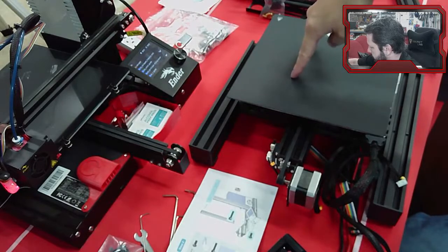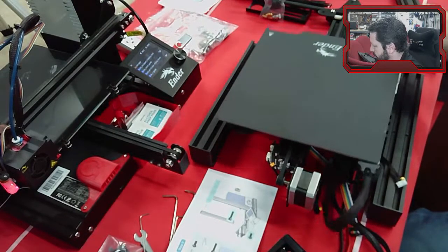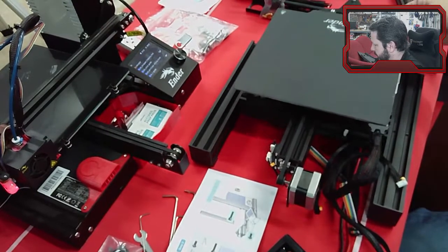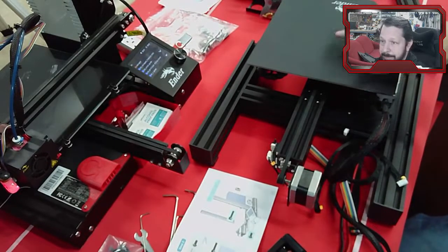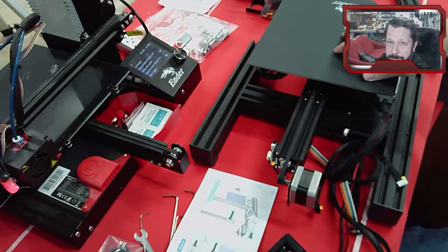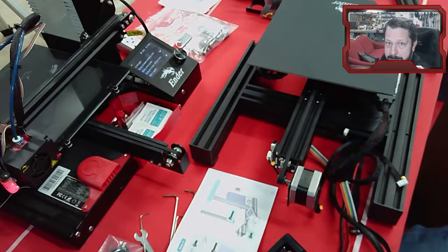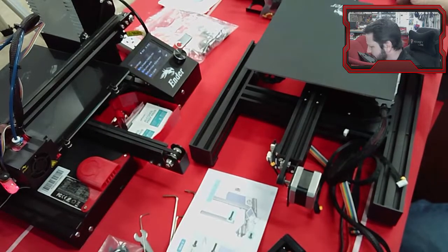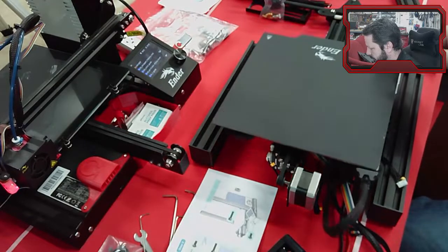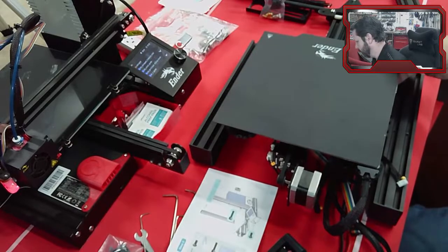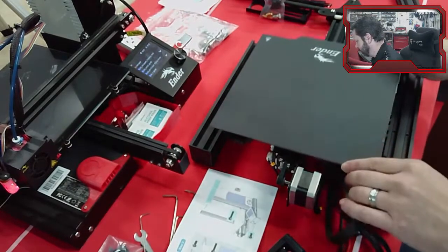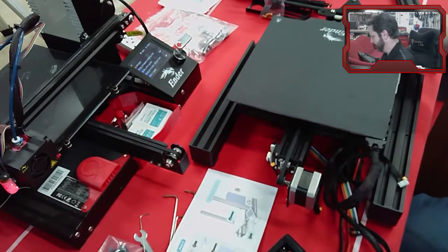There's 2 right here, and I'll try to get this a little smoother because it's definitely got a flat spot. I can feel it every time it goes around. And if I can feel it, then that means the prints will feel it also as they move past that flat spot. I may even have to replace the wheel. I don't know. Usually you can just loosen them up and they'll go back to normal. But whoever set this guy up cranked down a lot on the eccentric nut.